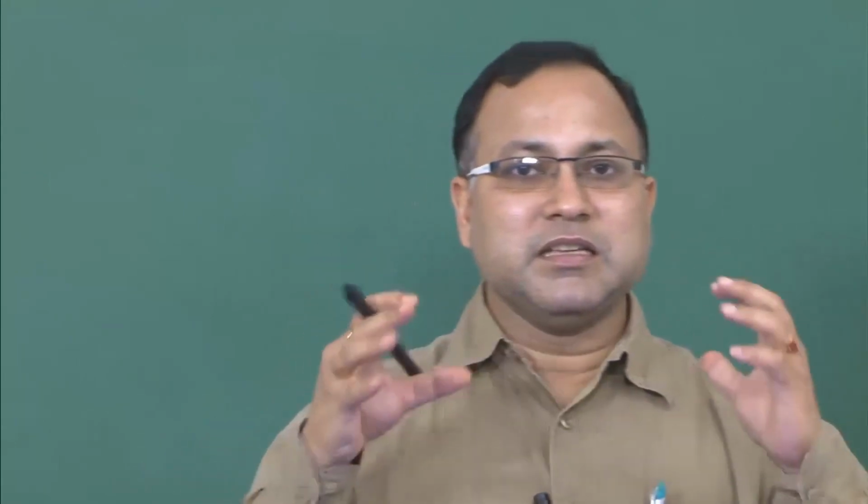So, this is very important, and you might have observed this thing without knowing. Now, you know why this kind of tension crack is really happening in the soil. You will not be getting this kind of tension crack in cohesionless backfill. You will be getting tension crack in cohesive backfill when you have cohesion, because you are getting some development of tension at the top portion of the wall.